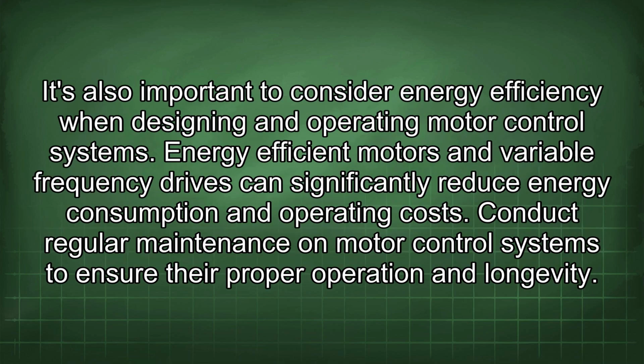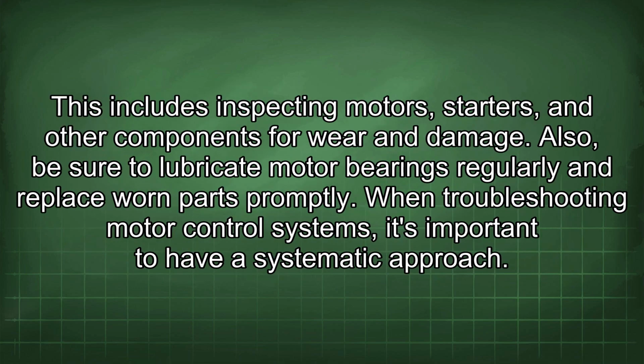It's also important to consider energy efficiency when designing and operating motor control systems. Energy-efficient motors and variable frequency drives can significantly reduce energy consumption and operating costs. Conduct regular maintenance on motor control systems to ensure their proper operation and longevity. This includes inspecting motors, starters, and other components for wear and damage. Also, be sure to lubricate motor bearings regularly and replace worn parts promptly.